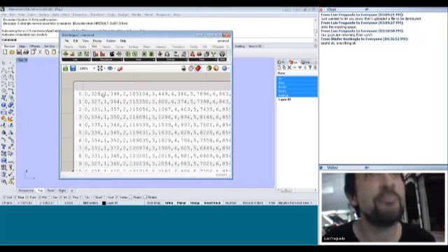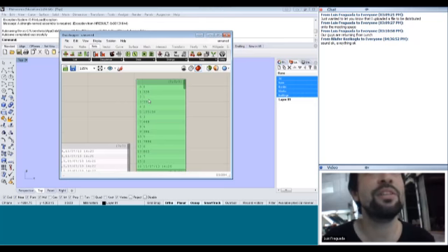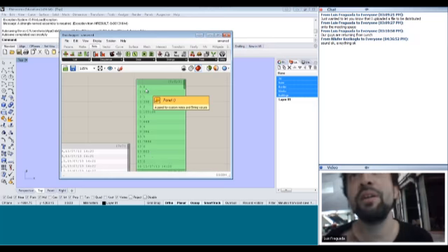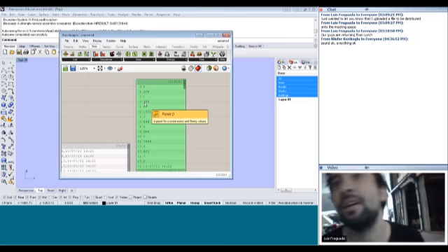When I split this up and I get a list for each of my time signatures, 0, the first item, is just the ID of the temperature sensor. 1 is the value. And 2 is the ID of the humidity sensor. 3 is the value. So we're only interested in the odd elements here, which are the actual values of our sensors. Maybe what would have been better is if we would have written what the sensor was there, but that takes too much memory in the Smart Citizen.